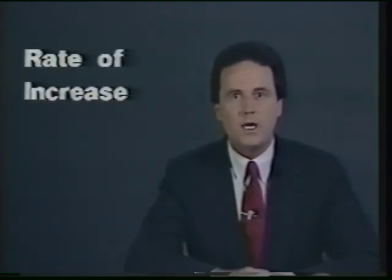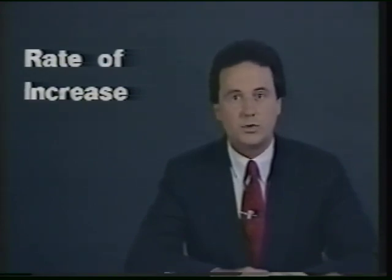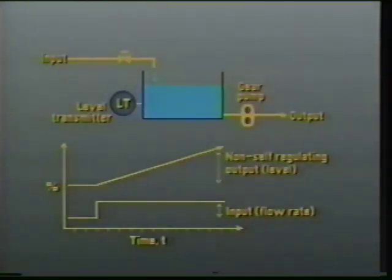The only way to assign a numerical process parameter to a non-self-regulating process is to measure the rate at which the output increases in response to the change in input. This is necessary in order to ascertain how much time is available to respond to the increase before the constraint is reached, since exceeding the constraint usually leads to an undesirable situation. This rate of output change can be either linear, which is to say constant, or nonlinear, which indicates an accelerating rate of change.